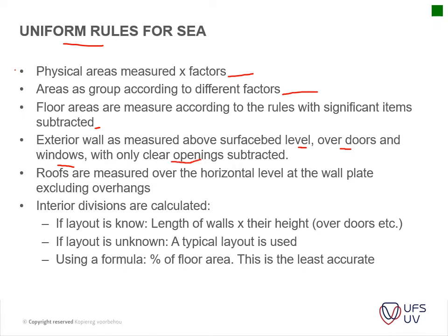Okay, so the rule of thumb is you measure your walls over the doors and windows, except if it's a substantial opening. Okay, that is a relative term, and I think you would ask the question, when is it a big enough opening? The rule of thumb is usually when you have sliding doors, windows, that type of openings, and that's more than a standard double door opening.